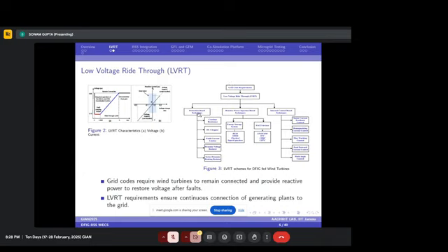So we have different techniques for maintaining this low voltage ride through. One is the protection based techniques, another is the reactive power injection based techniques, and the other is the internal current and control based techniques. Within the protection based techniques, different external devices are integrated into the network to assure the protection of the network, but they are not relying on controlling or maintaining the voltages.